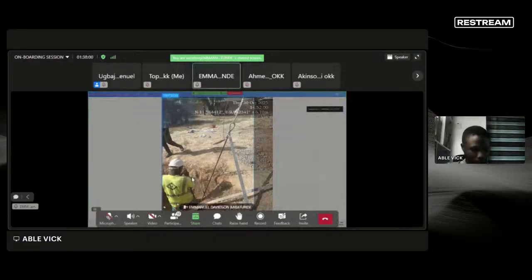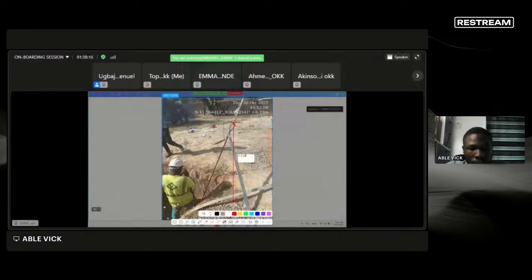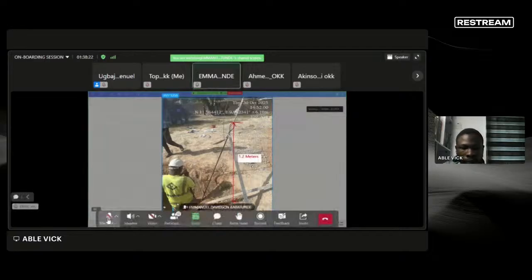Let me give you a short solution to save issues while working. From the tip of this guy to the ground, leave it at 1.2 meters, and in alignment with the 5-meter line, that is, with the tip of the excavation and with the tip of the base plate. Once the iron rod is at 1.2 meter height from ground level, brace it there and backfill.